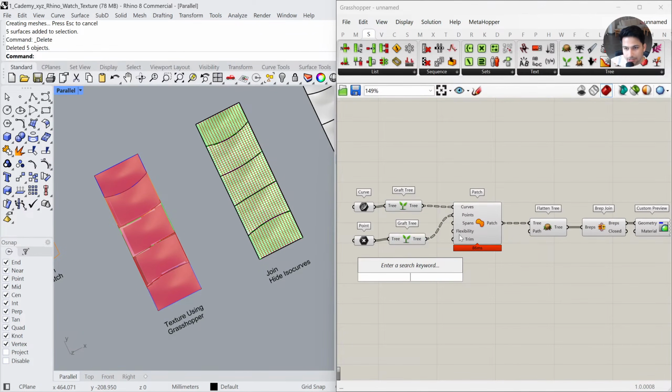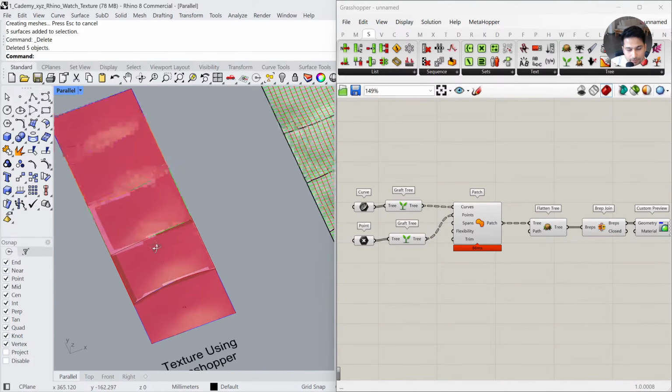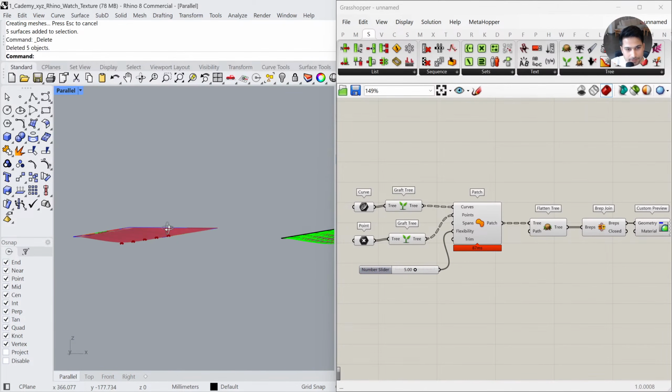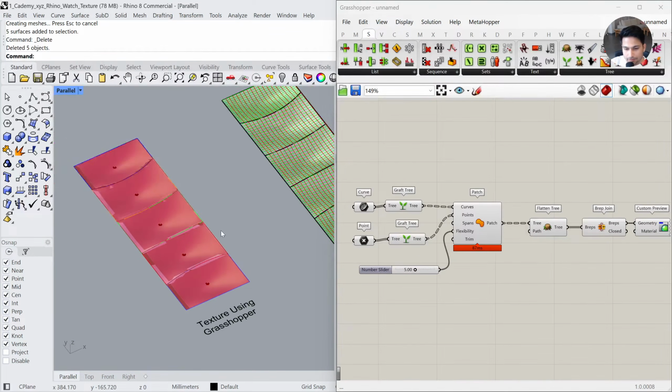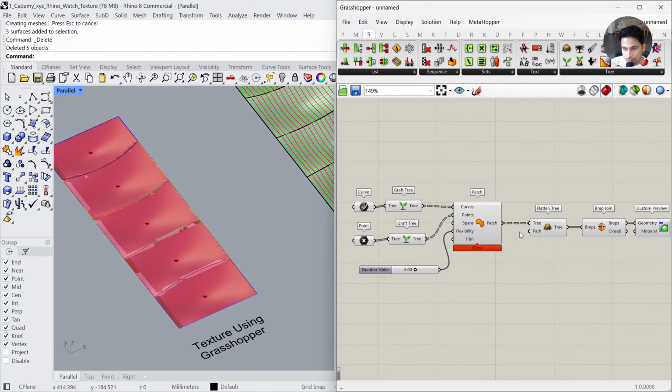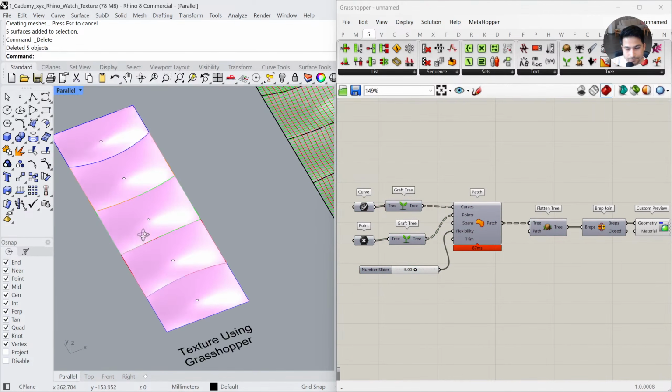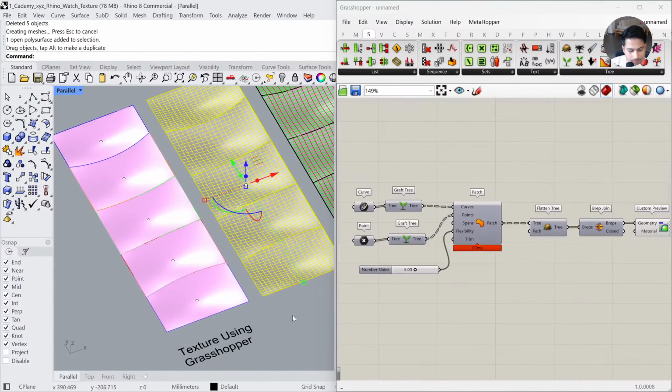You can also change the flexibility parameter to make it more flexible by adding a number slider. So just double click and write 2.50 and connect it to the flexibility input. So you can change the flexibility of the surface. Okay, so let's say if I set the flexibility to 5, we get this output. In order to properly visualize it, you need to hide the previous nodes. Select them all, middle mouse button, hide. So if I bake it, you can see we have a single output.